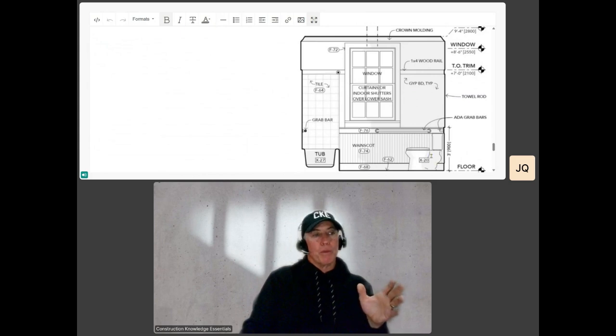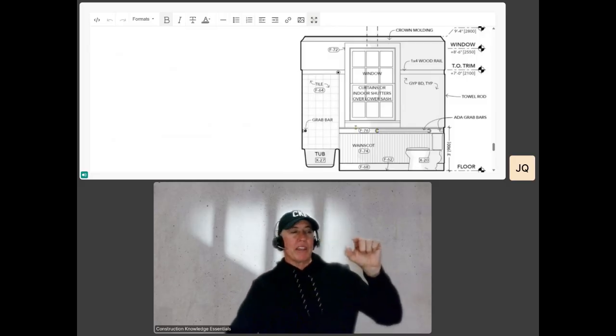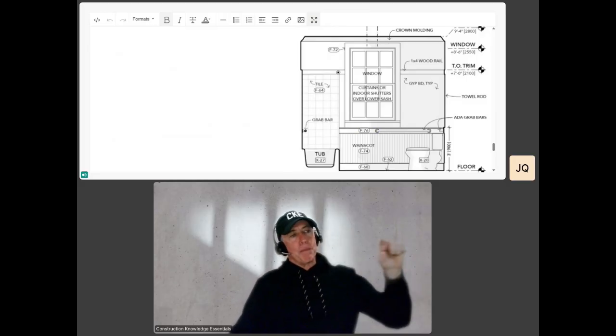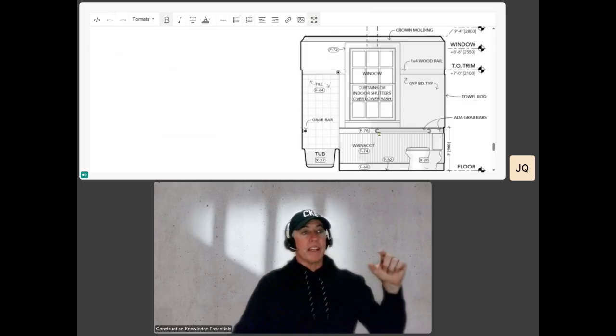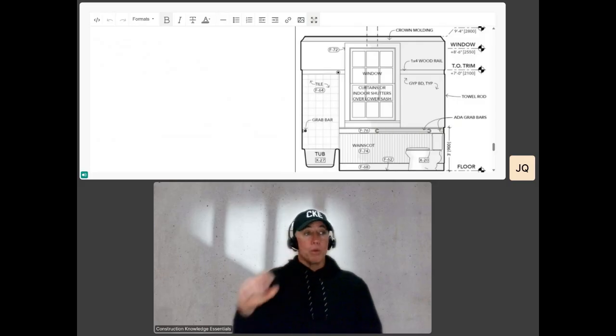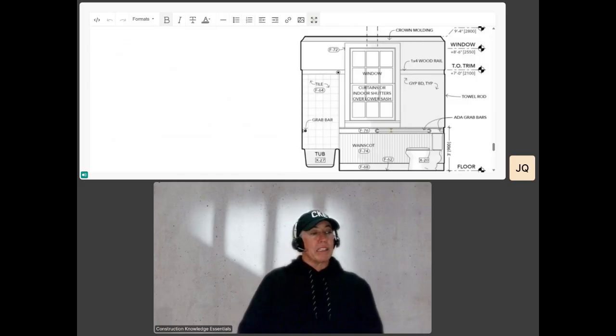So the commode is there. Then your ADA grab bar. We're back to F76, which would be our finish. So you can tell F76 is probably a border or a millwork of some sort that basically calls out and says, hey, we're going to call it this. And you can see where it shows the ADA grab bar that goes through it. So they wanted to make sure visually that that grab bar went through that trim. So it gave it a nice look. Base molding, F68. Floor, F62.